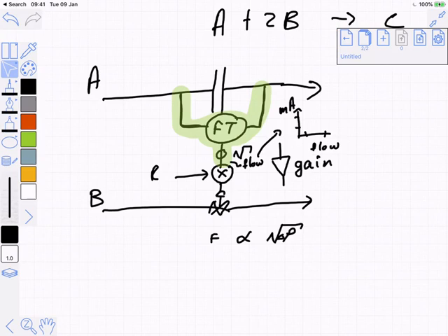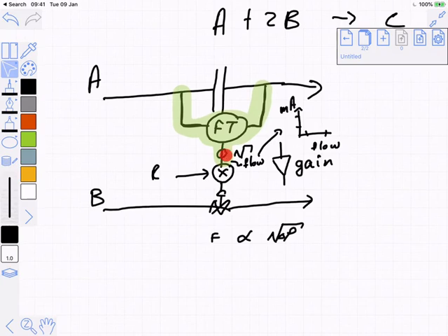And you'll see that some of the examples in the textbook actually resemble feedback control a lot more than this scheme. But I think it's really easy in this scheme to understand that it's because the manipulation doesn't affect the thing that we're measuring. Remember, we're measuring stream A, but we're manipulating stream B. And nothing we do to stream B will ever change stream A.